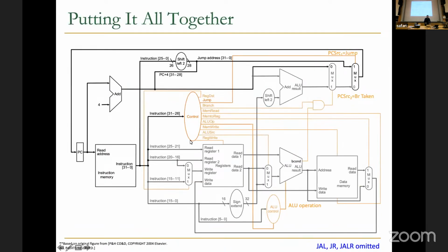So this is the full thing that we built incrementally, but we never showed the full thing over here, right? These are the instructions. But let's take a look at this branch condition logic because we just talked about it. So basically, the ALU gets these two registers and this multiplexer. You can see that the orange signals over here are control signals, and there's a control box that determines the control signals. And you can see a lot of these are intuitive.